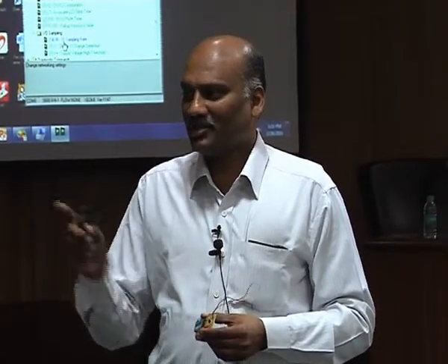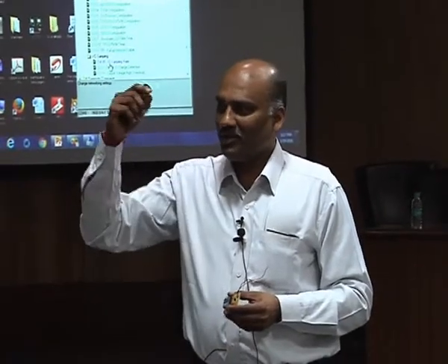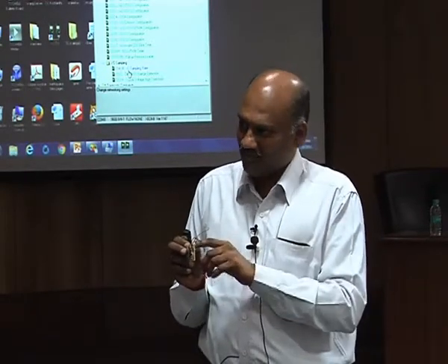The reference voltage is basically used for our analog to digital and digital to analog conversions, sir. So the basic voltage is 3.3, that is for the power supply of this one. The same 3.3 is being used as a reference voltage. It means the same value can be connected here. You can see the 14th and 16th pins.